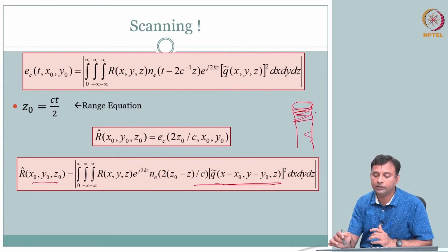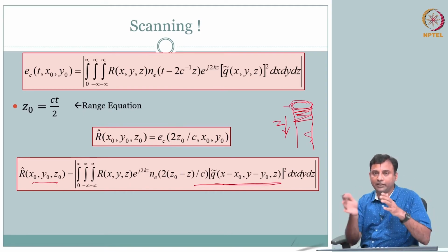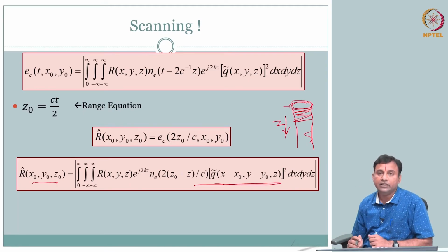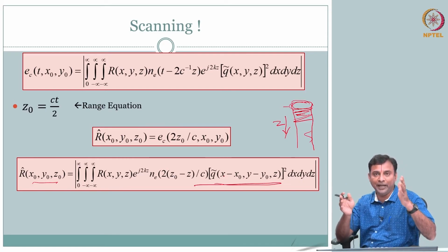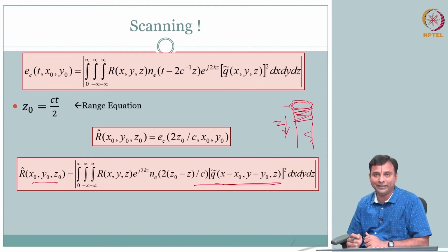This is my z direction, depth direction. The plane of the transducer is xy, for example, and it is directly sending a pressure wave in the z direction. Even if you take it like that, the simplest case, so that I can avoid all this main lobe, side lobe, Bessel function or sinc function.